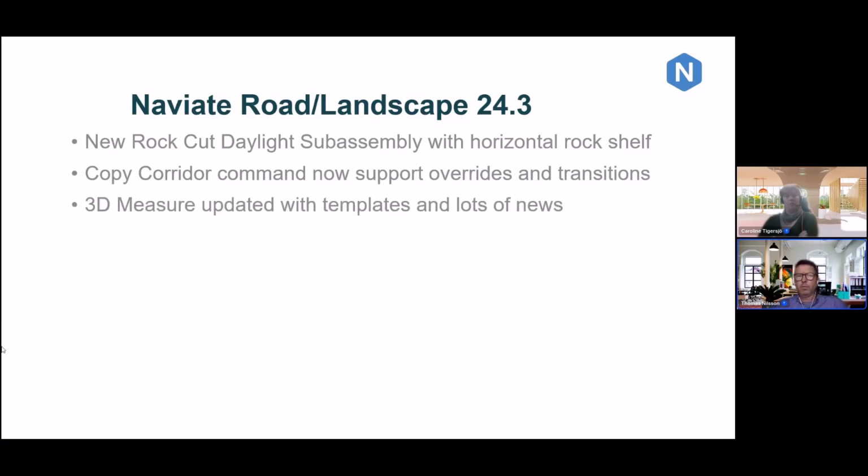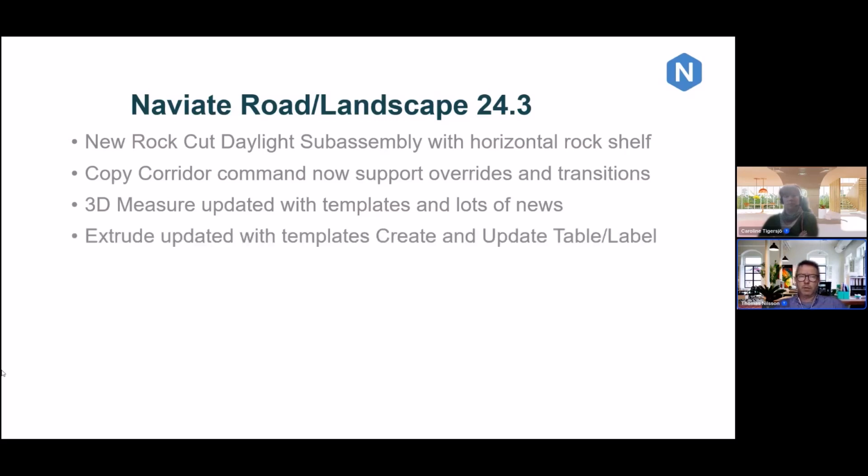We've done a lot of work with our 3D measure command, the one that inserts light posts or railings along feature lines. So we added a lot of features in there. The same with the extrude command, ability to extrude any kind of polyline shape along a feature line or 3D poly or so.